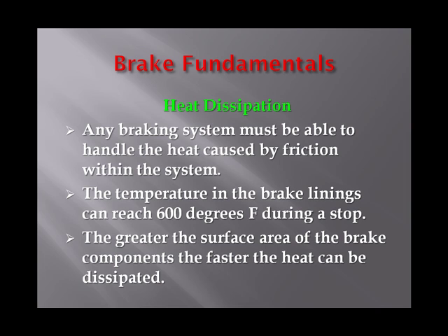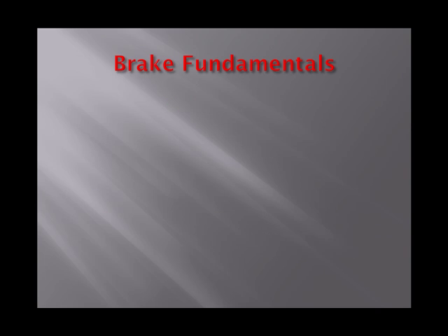Brakes that do not effectively dissipate heat will experience what's known as brake fade during hard continuous braking. The linings will become glazed and the drums and rotors hardened. Therefore, the coefficient of friction will be reduced and excessive foot pressure will be required to stop with the desired braking effect.